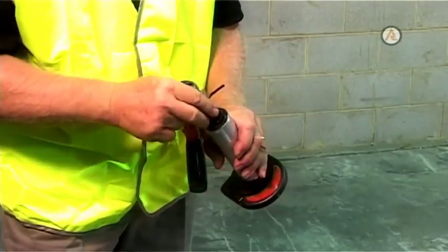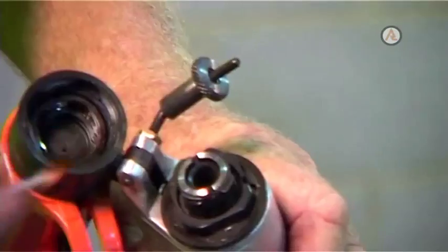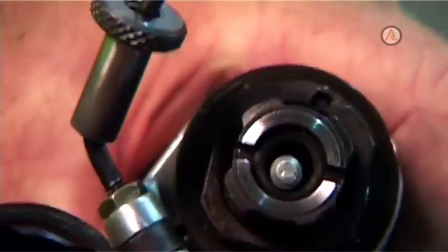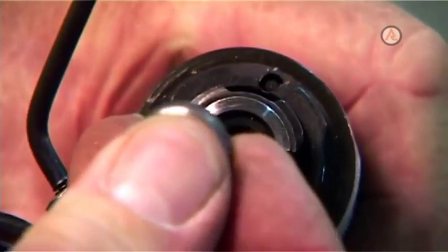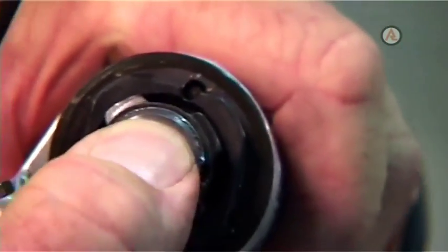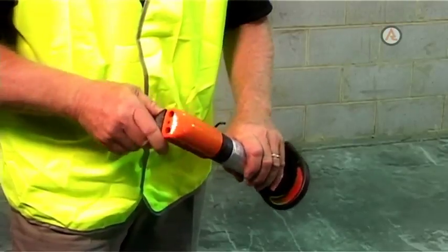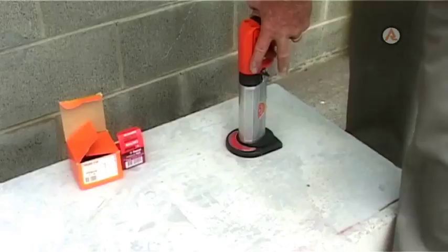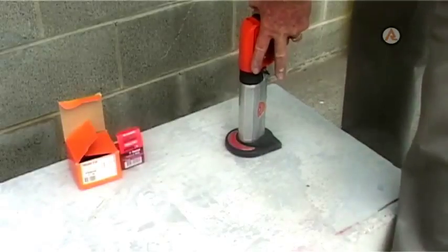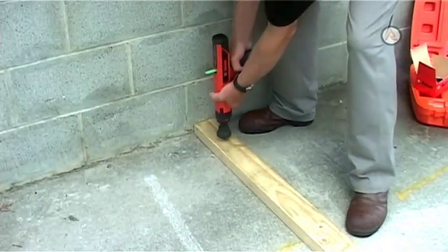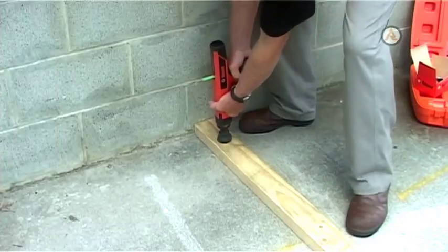In general, high-velocity tools are of a simple design that requires reloading of the drive pin and power load each time the tool is activated. Many high-velocity tools continued to be sold up until the turn of the century and can still be found in use on job sites across Australia. High-velocity tools have now been essentially superseded by new low-velocity piston-type tools.